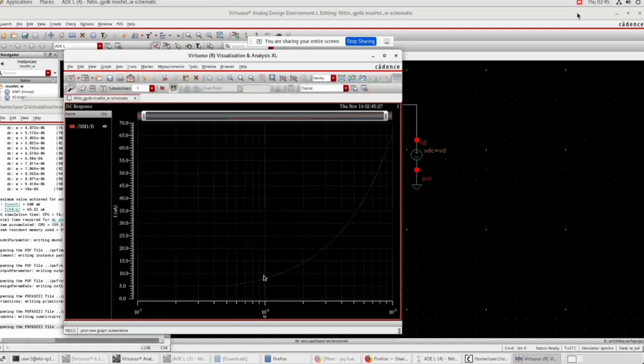this is the plot which I get, and from this I know that the current through the MOSFET should be 60 microampere. You can see that around 9u the current is around 60 microampere. By 9u I mean the W is 9 micrometer, and the length of all the MOSFETs is fixed at 400 nanometers.